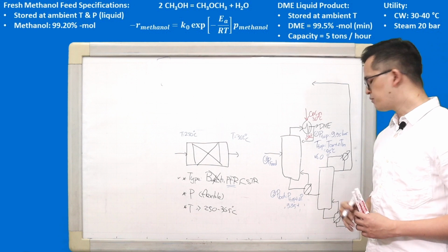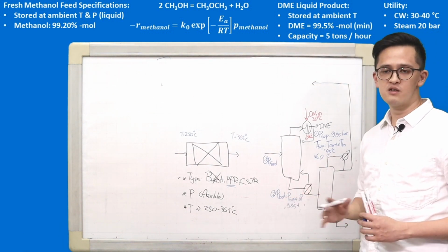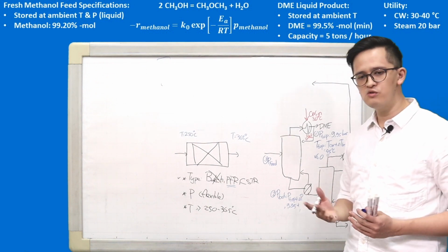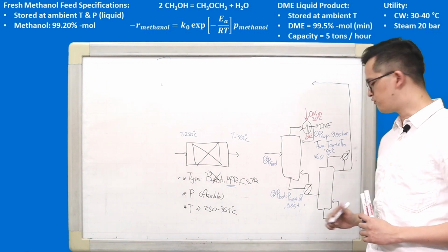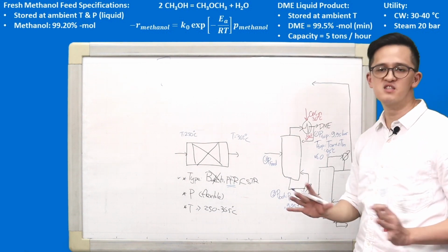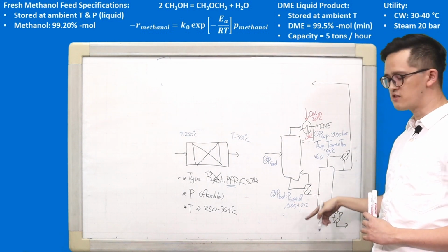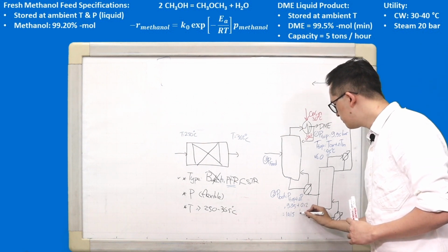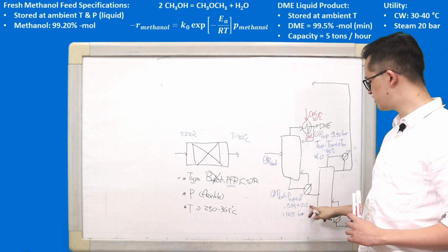So let me help you with the quick value that typically happens in the distillation column. Probably it's going to be around 0.2, 0.3, or at most 0.4 bar. I'm going to give you the explanation for those, so let me use one number just as a starting point. Okay, let's say I'm going to give an extra 0.2 bar as delta P, so that I will get the bottom pressure as 10.15 bar. Now the question is, where is this number coming from?